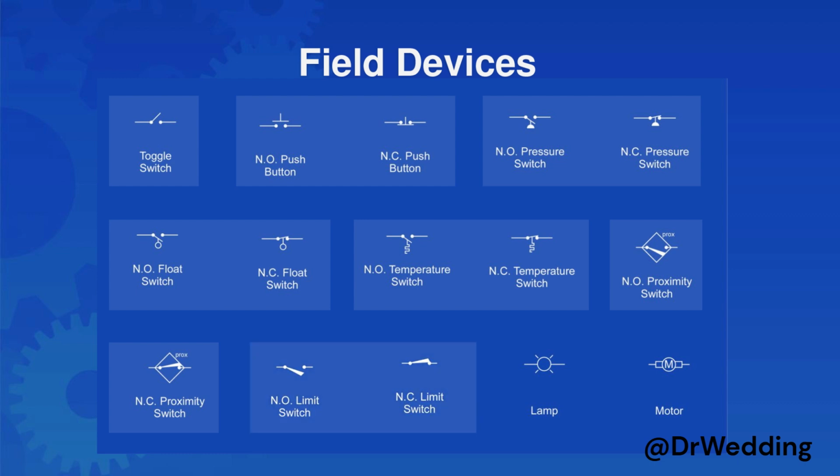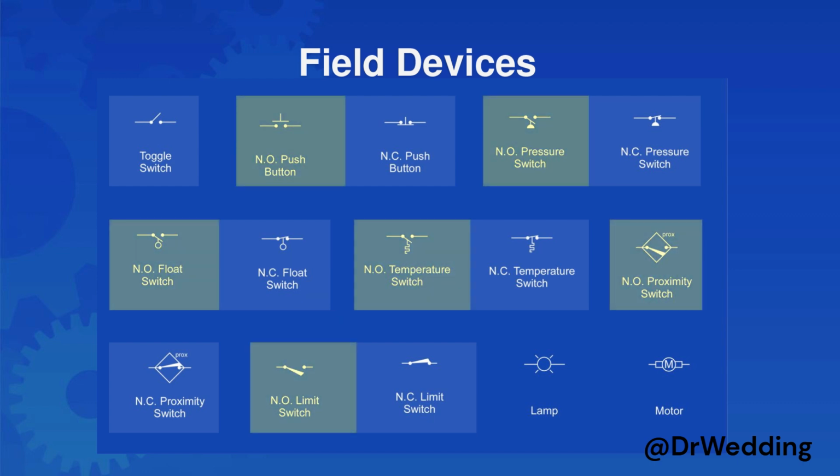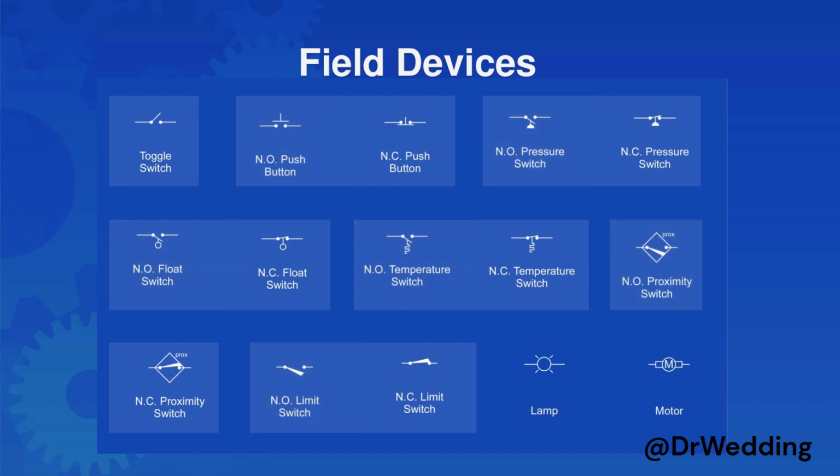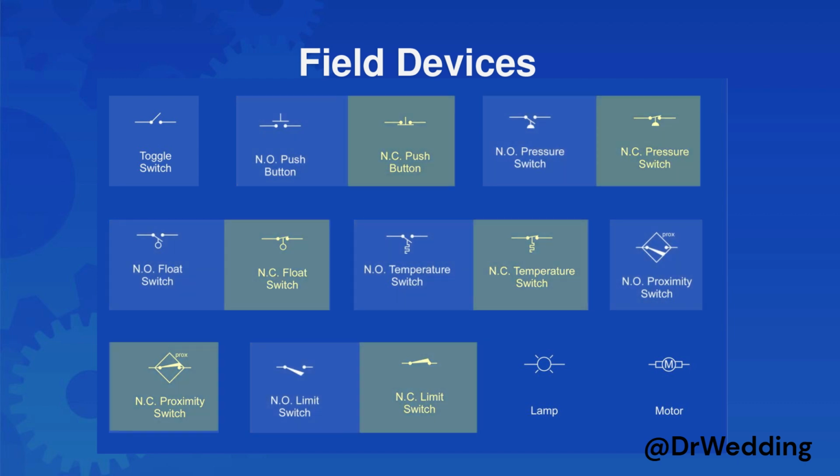These input switches may be normally open, meaning they are open at rest, and when a force acts on them, they will close and complete the circuit. The input switches may also be normally closed, meaning they are connected at rest, and when a force acts on them, they break and open the circuit.